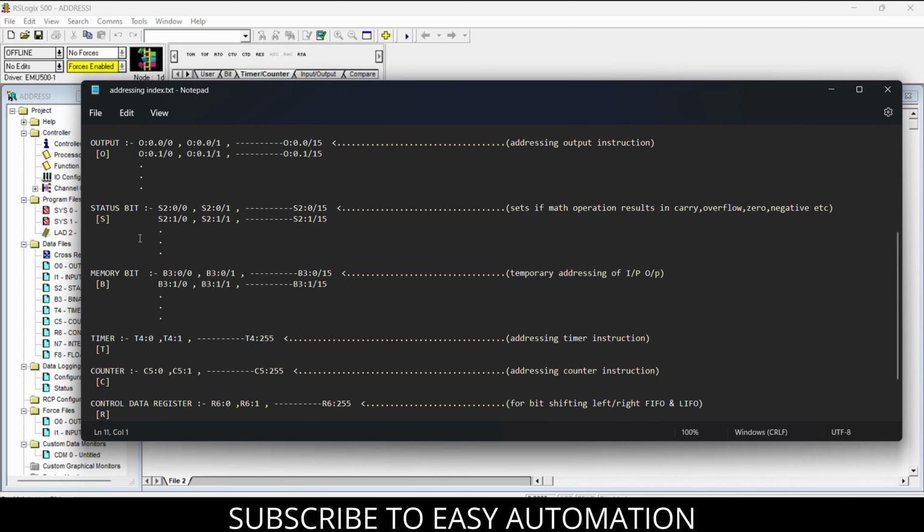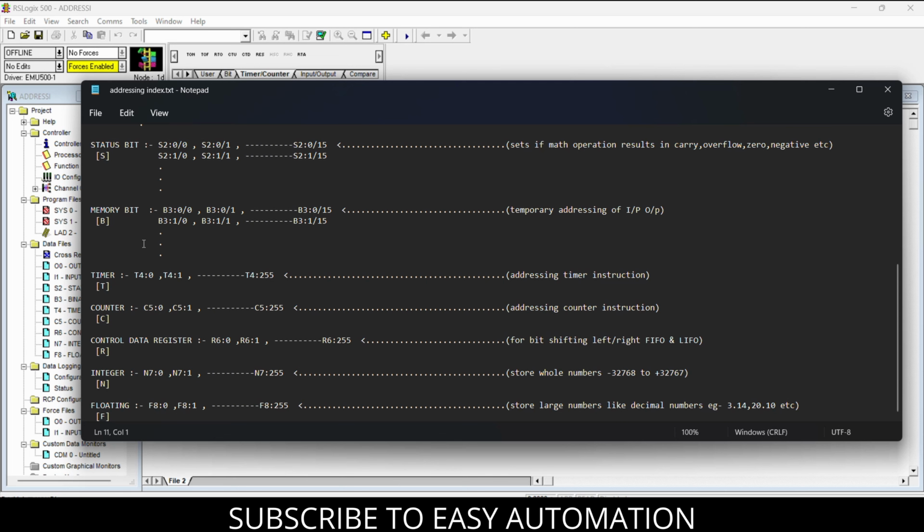Next are status bits, which are used for math operations, like to show carry, overflow, zero, negative, and that kind of math status. Next are memory bits, which are temporary addresses for inputs and outputs. Next is the timer, which is used for addressing the timer instructions, and the timer addressing ranges from T4:0 to T4:255. Next is our counter, which is used for addressing our counter instruction, which starts from C5:0 and goes up to C5:255.